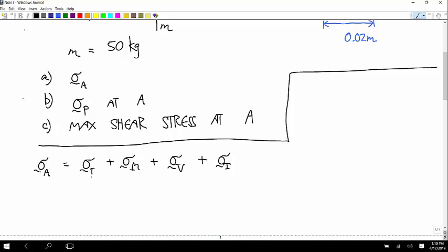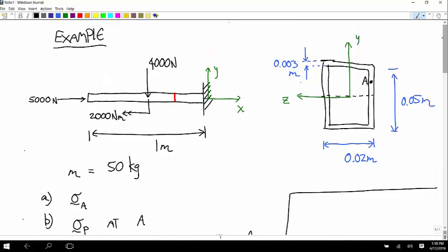Let's start by calculating the internal loads at that point. Usually when we calculate internal loads, we calculate them as a function of x. But since we're given a location, an x value where we want to calculate these, we might as well just make the one finite cut and calculate those without any functions.